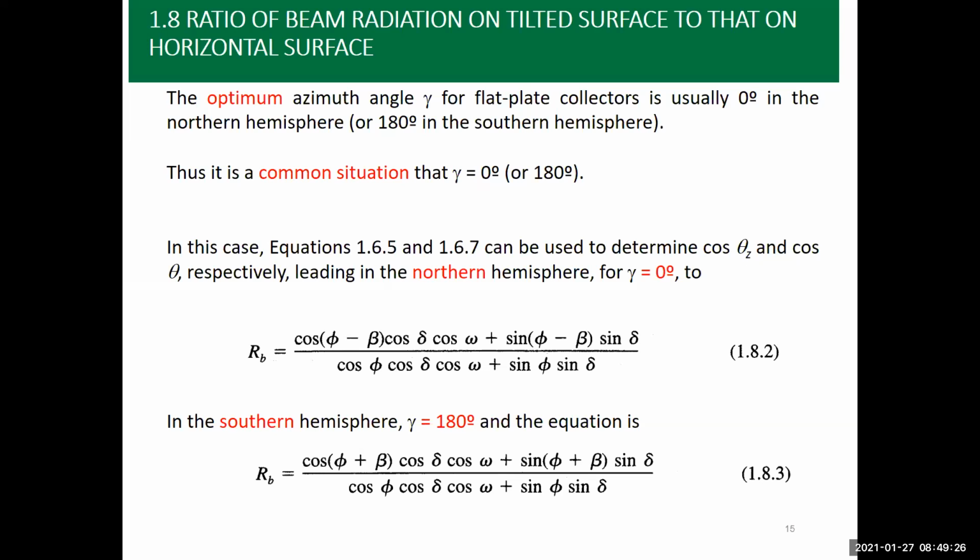They are basically, again, that belongs to our research area where we are doing experiments on desalination systems using solar energy. You'll find that there we have a PV system for electric generation, and we have evacuated tube collectors and a flat plate collector, and all of them are facing due south. So what we do, we check what is the south direction, and we make all our units face south. So the value of gamma there is going to be equal to 0.